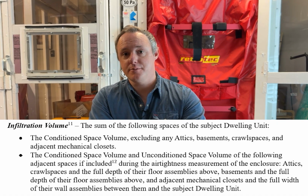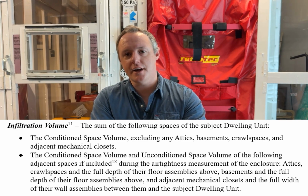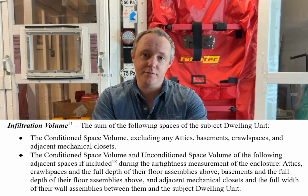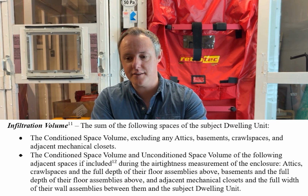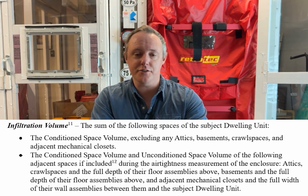For you to include an attic as part of your infiltration volume, and infiltration volume is a term that the ResNet 380 standard uses, that is your air barrier that you are allowed to test. So you have your condition volume, which is the condition space that's deliberately served by the HVAC system. The infiltration volume might have some extra parts that you can also include. For an attic to be included as part of that infiltration volume, a couple of things have to be true.